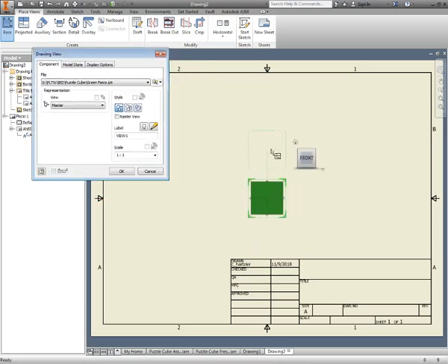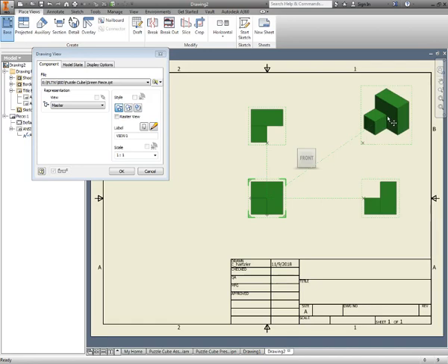Alright, so here's my main piece. That's my front view. Now I want to click on the top left side of my paper. That's going to be for my top, and off to the right, that's my right side view. And if I go to the top right corner, that should be the isometric view. If for some reason your front is not correct, you can rotate this box and it will change all of these views until everything is correct.